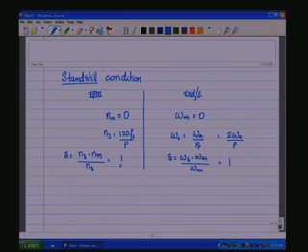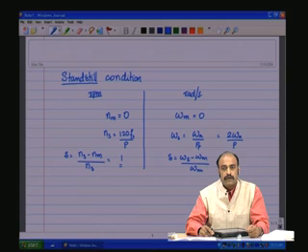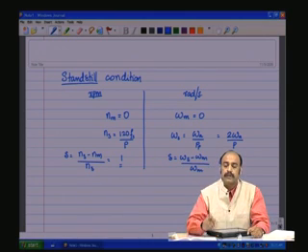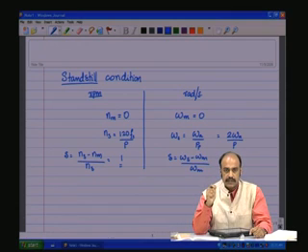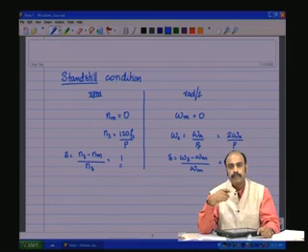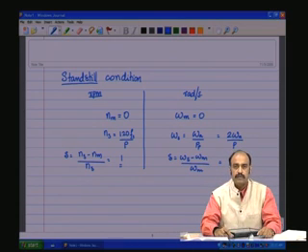So when the slip s is equal to 1, the relative motion between the rotor conductors and the rotating flux is maximum, and that is ns itself, and therefore the induced voltage in the rotor conductor is going to be very high, but the rotor is short circuited, and therefore instead there is going to be a large current till the motor picks up speed and the relative speed between the mechanical speed and the synchronous speed reduces to a smaller value.